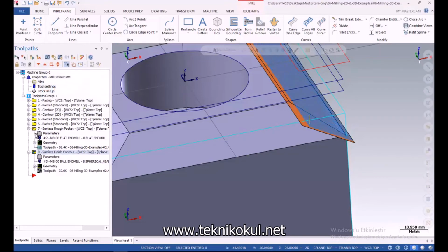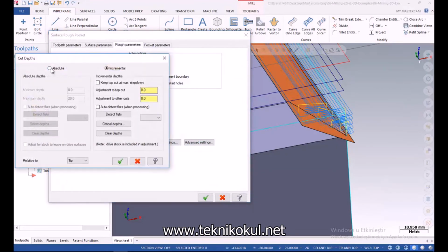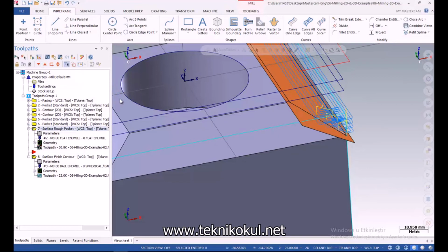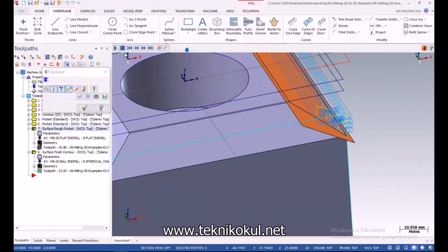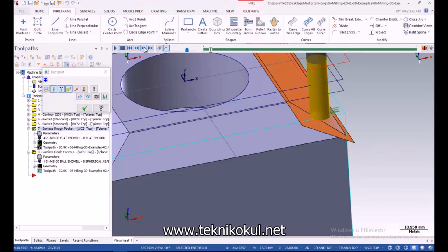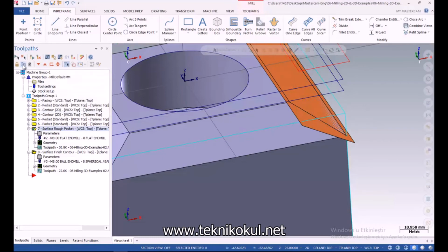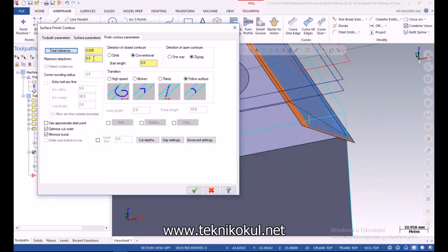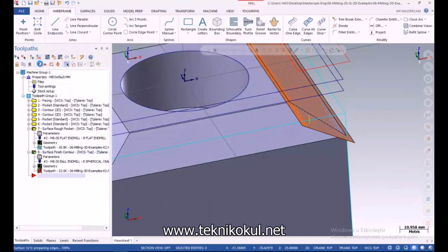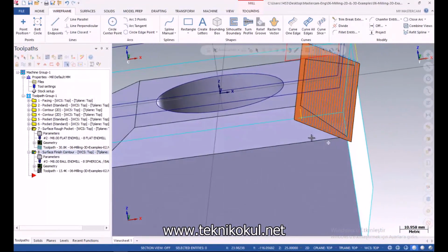So I can do the same things, but by roughing operation. I'm gonna select that one. That is the minus 0.1 to minus 10. That is my Z boundary. So I'm gonna click OK. I'm gonna regenerate my toolpath operation. So I'm gonna backplot simulation. Yeah, after ramp, that is my Z position, Z minus 0.1. So that is not going to be a waste of time for that toolpath. Okay, I'm gonna change it a little bit because that is not so good. Okay, that's perfect toolpath.